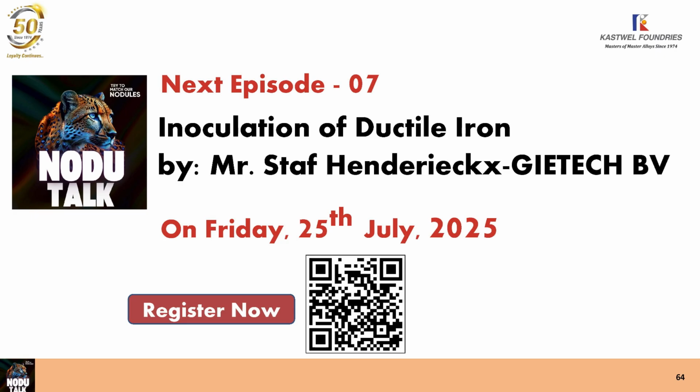That's the one thing. The second thing is that 30 degrees, and in small castings it may be even 50 degrees, is very important, because during the pouring you will have some inclusions. You will have some sand inclusions, you can have dross. Later this year, we will talk about the problems of inclusions in ductile iron, and dross is the most important one there. Every casting during pouring makes dross.